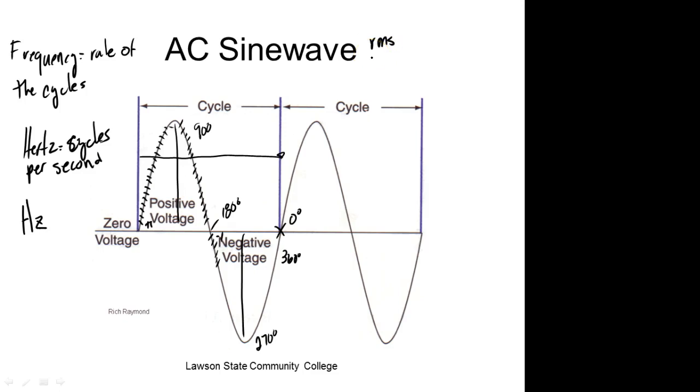Your meter measures RMS, which stands for root mean square. But that definitely is the root of the means of the square. A mean is an average, right? You understand that? Mean is another term for average. So what they did is they come up here and they squared every measurement along this thing, and they did equally spaced measurements. Well, every time you square a negative number, it gives you a positive. Then they take the average of that, and then they take the square root of the answer, and that's what they do to calculate RMS.